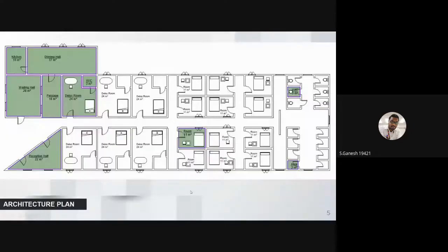Okay, so the first part which you want to know in drawings is the architectural drawing. What mainly is an architectural drawing? It is going to show you a layout, or a plan of which geometry the building is to be prepared with. It will show you the room dimensions, the ground area, the floor section or elevation view. All this will show you the complete architectural plans.